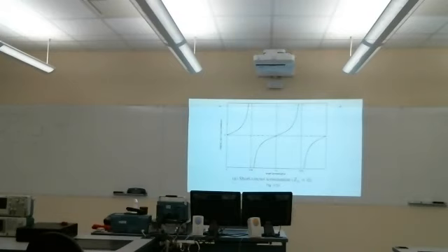Because our voltage and current are changing along this line, our impedance is actually a function of distance, Zin of L. Again, at low frequencies, if these are a pair of wires, if you measured the impedance here, it would be equal to ZL. But something is different at these higher frequencies, where it takes time for the voltage and the current to travel down our transmission line for that propagation to take place.